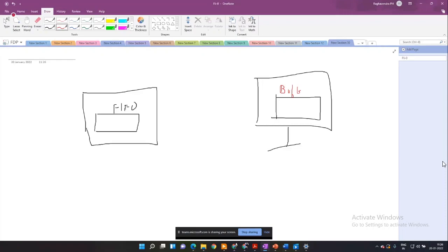So what happens is, your USRP gets the data from the antenna, processes it, and starts filling up this FIFO, and simultaneously it starts sending data to your buffer in your computer. Your computer buffer starts getting filled up in the RAM, and then if you want it displayed, it will display it in any format you want. You want to see the signal, it will show you, depending on how you program it. You want to see the constellation, you can do that, anything that you want.